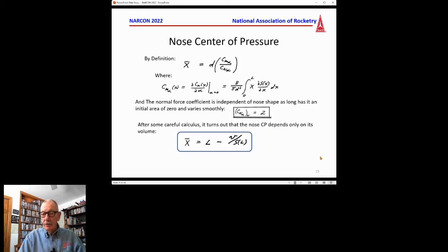They're not going to cause blood if they poke you. So they all actually end up with a zero area at the tip, and that's the real meaning of that coming to a point. So using those assumptions, using some calculus, first of all, the Cn alpha is really just a function of the area, and that can be added up. There's some simple numbers for the cone.